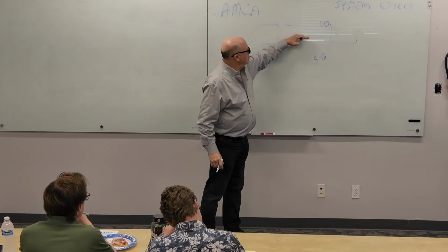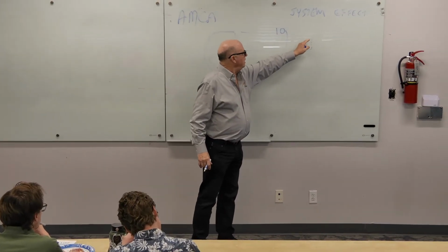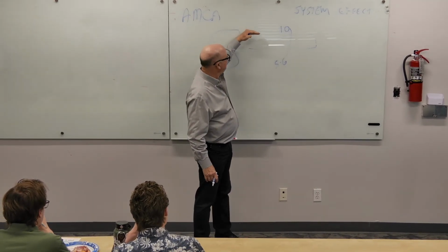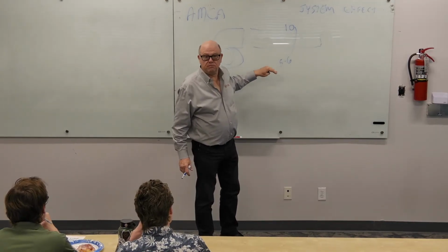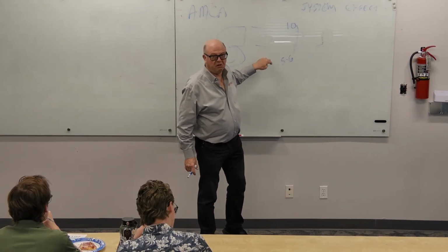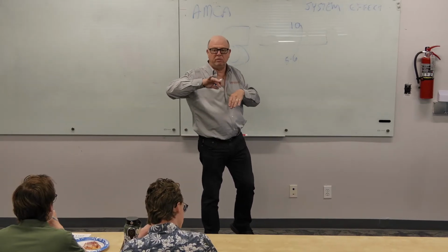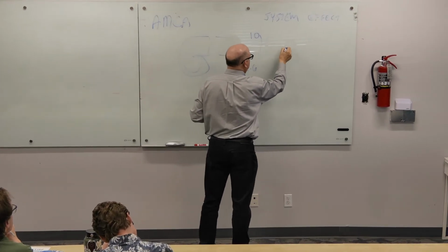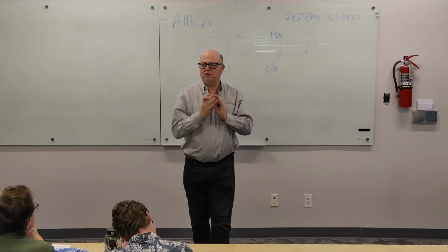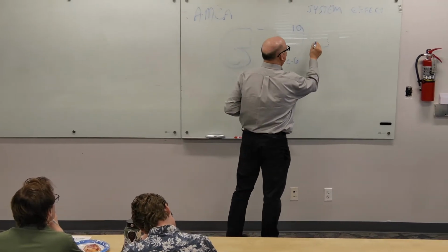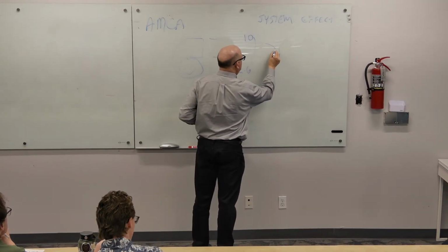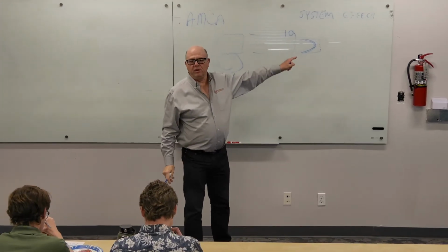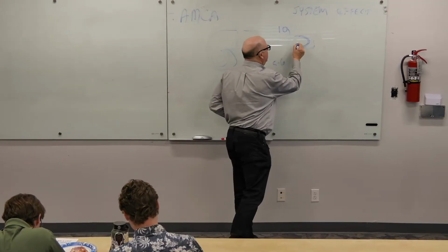Well, for one thing, the air going through this duct is not uniform through the whole duct. There's friction along the edges. This lined duct, there's probably even a little more friction along the edges because, you know, that insulation is kind of rough. But you'll have a velocity profile out here somewhere, and one of the reasons they arbitrarily picked 10 duct diameters is because the theory was by the time you got there, it would be an even duct profile like that.